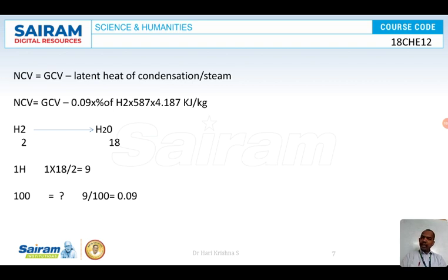So for 100 grams, simple cross multiplication gives 0.09. So that is how you get 0.09. So NCV equals GCV minus 0.09 into percentage of hydrogen into 587 into 4.187 kilojoules per kg. This is what NCV is. So thank you. Let's meet again in our next discussion. Thank you.